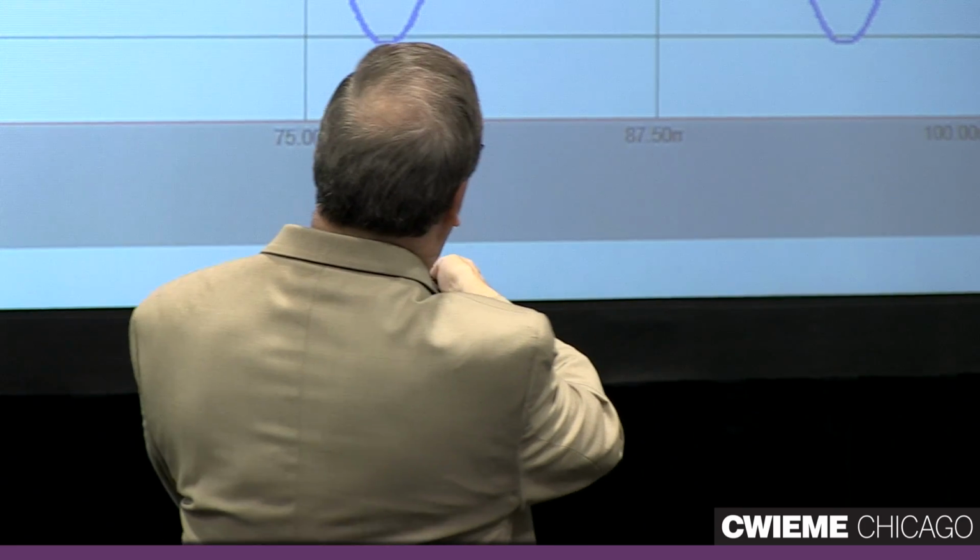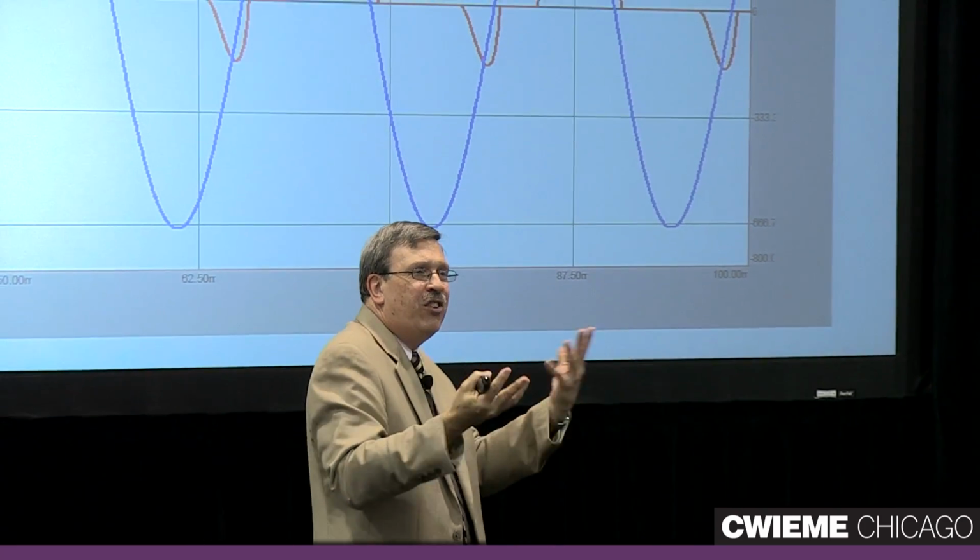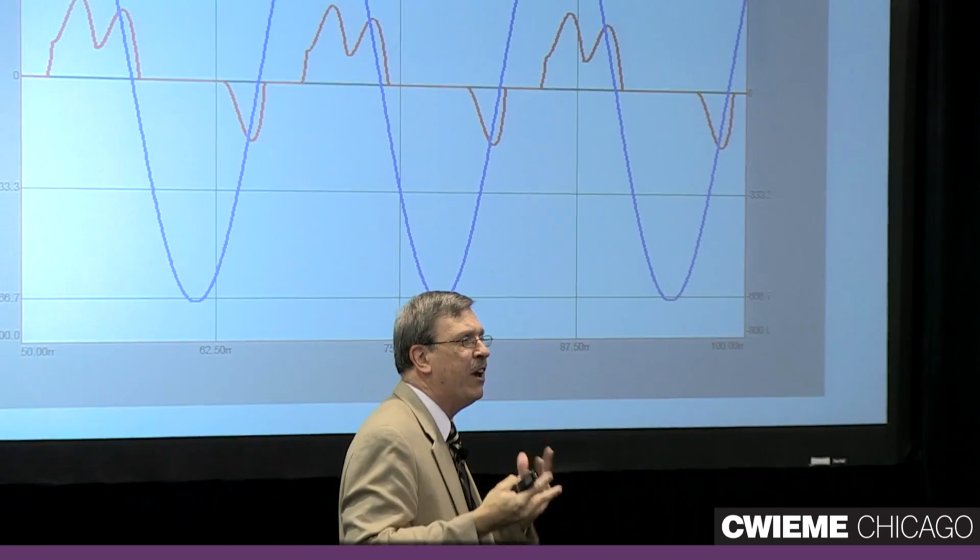Roughly. Maybe we'll make it 10. Suppose you have a diode right here that sort of became smoke. It no longer is there. That's an open part of the circuit. If you take a look at the current that's coming in here now, this is what it looks like. You get 2 bumps here part of the time, and 0, then just a single bump over here. So it's sort of like a mix of that single phase and the 3-phase type of current.